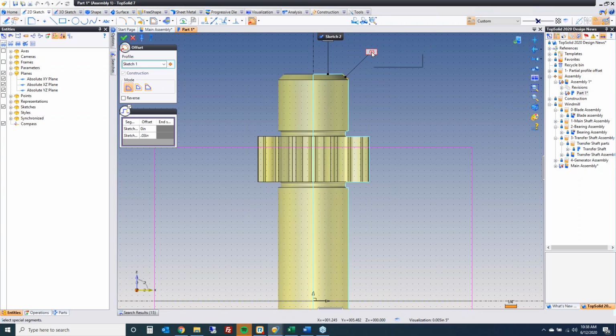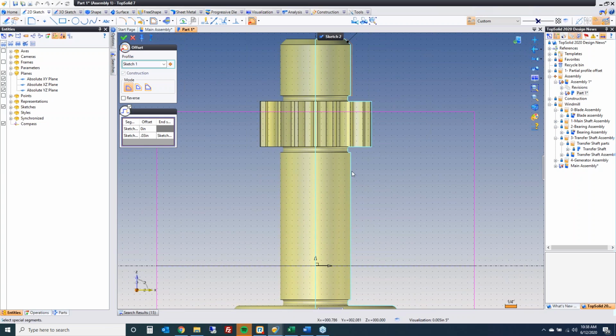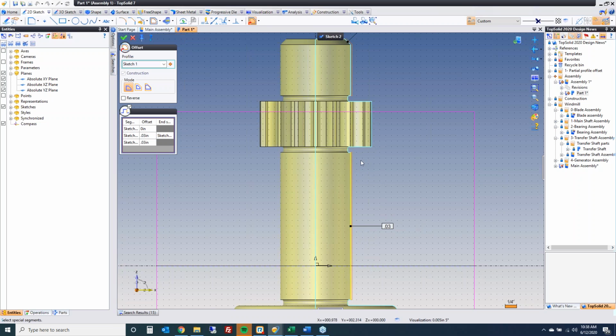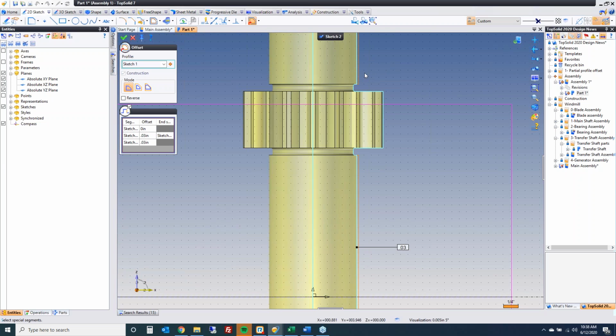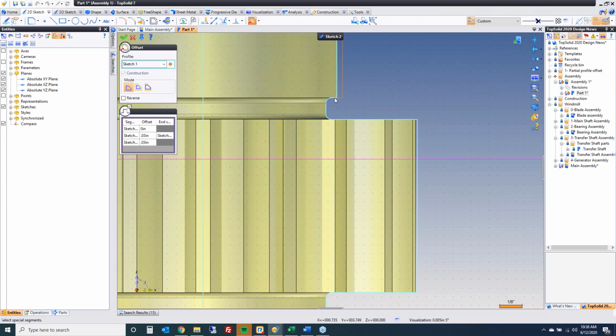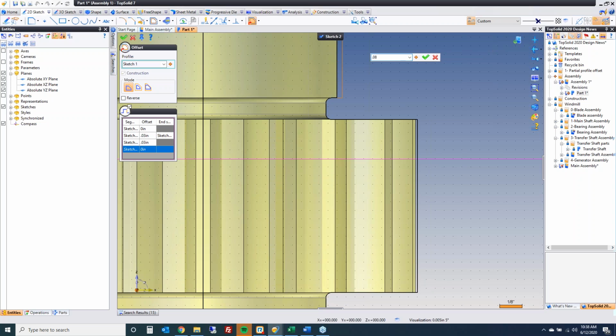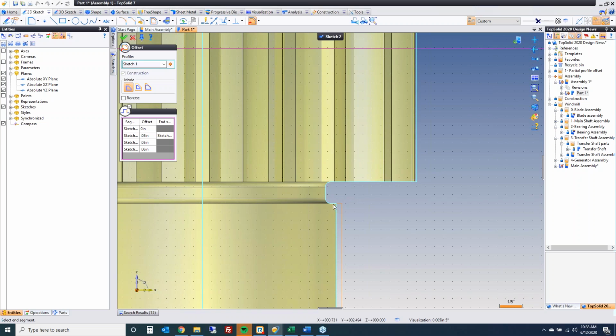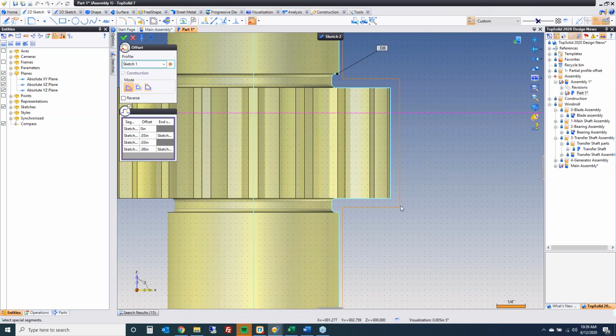Then this is where the improvement comes in. If I right click on this, I can say I want that 0.03 until that segment. Kind of cool. I'm going to go to here. I'm going to set this to 0.03. So notice right now, I have a custom offset, that's perfect. Now I'm going to add another one right here. This one is going to be, let's say, 0.08. Okay, and I want this until this. And notice it even solves the collision of geometries there, and we are getting custom profiles.